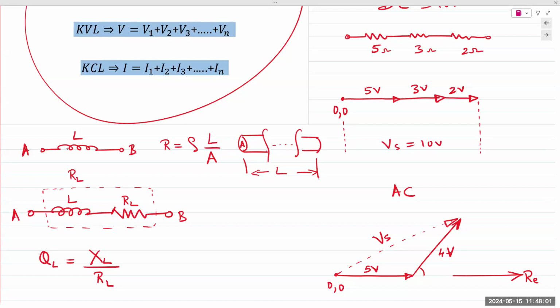Real life, RL is typically less than 5 ohms, around 4 or 5 ohms. So the labs are written with high quality inductors. We did not have low quality inductors at the time. So what you do in those labs, the lab write-up states, you add an external resistor in series with your high quality inductor to simulate or model a bad quality inductor. You guys with me? You're using an external resistor to simulate a bad quality inductor.